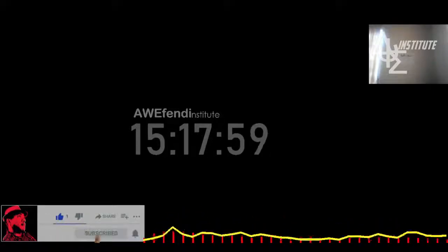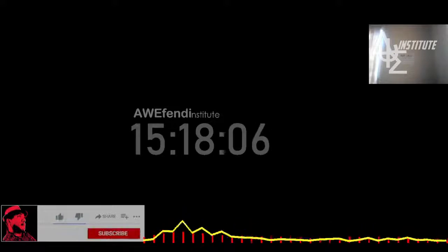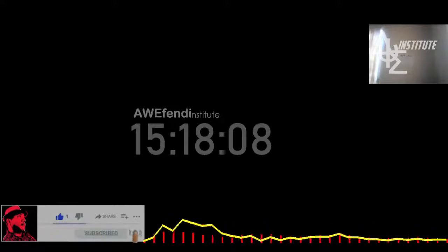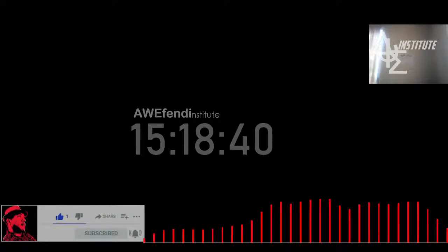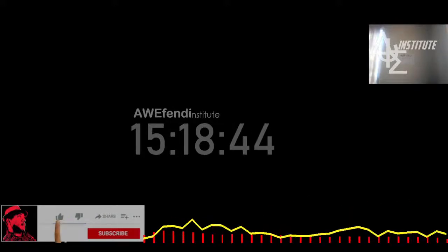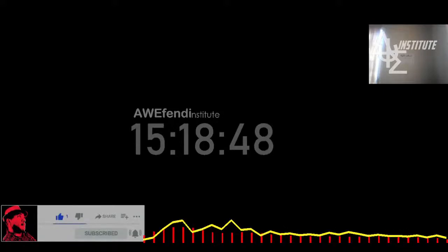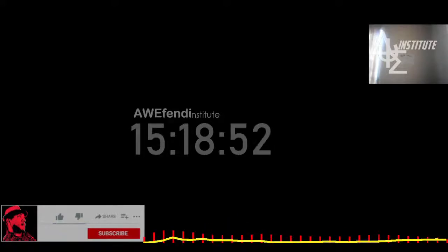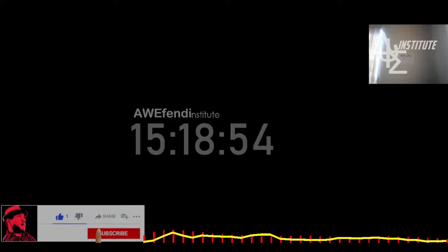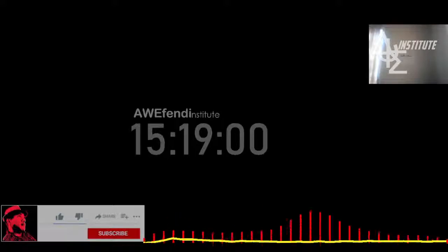Good. So the last demo I want to show you today is, again, this IGBT, and we're going to be looking at pure isothermal fluid flow calculations: horizontal cooling channels, ribs. Then we have vertical ones. Then we have some pins, and as the last one, there's these super thin channels that are basically guiding the flow all the way from inlet to outlet. And so we just want to see which one behaves the best in terms of recirculation zones and pressure drop.